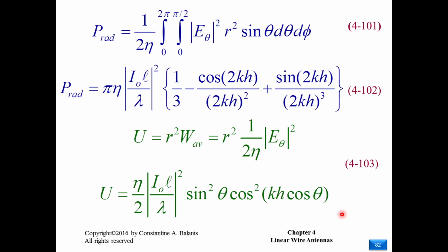In order to study the situation, we would go directly to calculating the radiation, and the radiation would be E square multiplied by ds over a half sphere. Why? Because there is no radiation in the lower half space. So phi is integrated from 0 to 2 pi, but theta is only from 0 to pi over 2.